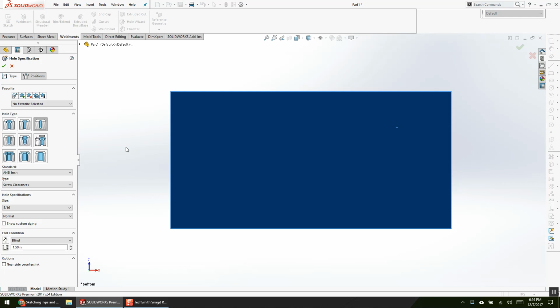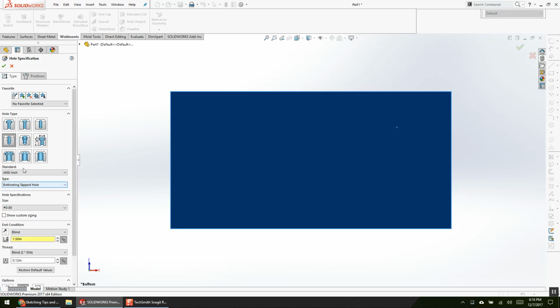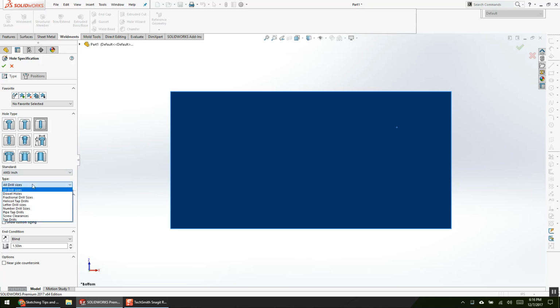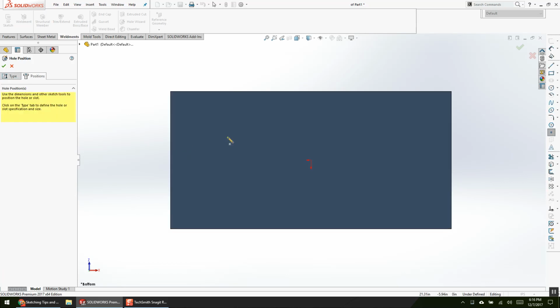It's U. And say I'm going to put tapped holes, which probably actually don't work very well in wood. So we're just going to do a fractional hole of 1/4 inch. We're going to use self-tapping wood screws. We're going to go down 1 inch in my positions. All right. Now I got to put positions on here, and I want to limit my liabilities.